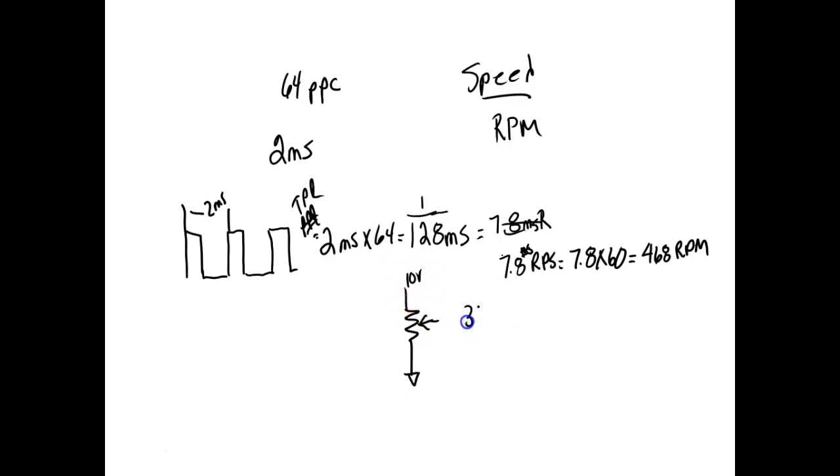We said we had a 350 degree pot. I think ours turned out to be 300 or 320. So I'm getting degrees out and putting volts in. Our transfer function is out over in, 350 over 10. So that would give us what?